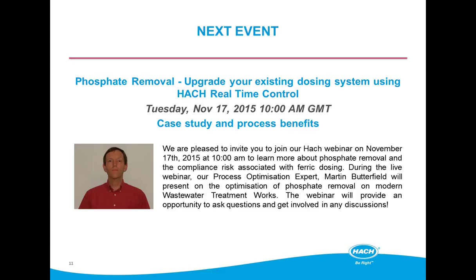And I think that probably leads on. There are three other questions we've got here. Trying to work out which is the best way to ask them. One question that's come through is, what happens if we don't have any ammonia measurements on either the inlet or the outlet? Yeah, well, if you're providing the correct control, you need to understand what your ammonia loading conditions are, because that does dictate what your DO set point should be.